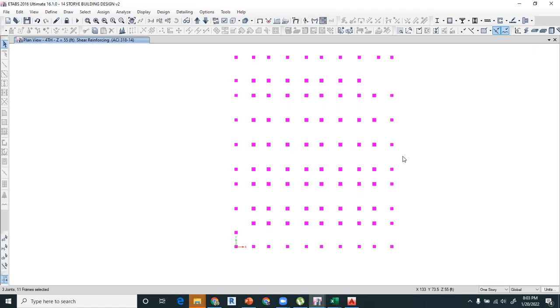And then we have done our column design, in which we use the values from the ACI code, that is maximum limit 8%, minimum 1%. And then we have calculated the ties, and we check the minimum reinforcement spacing and the maximum reinforcement spacing on the column. We will be doing all of these checks on the column tomorrow, right?